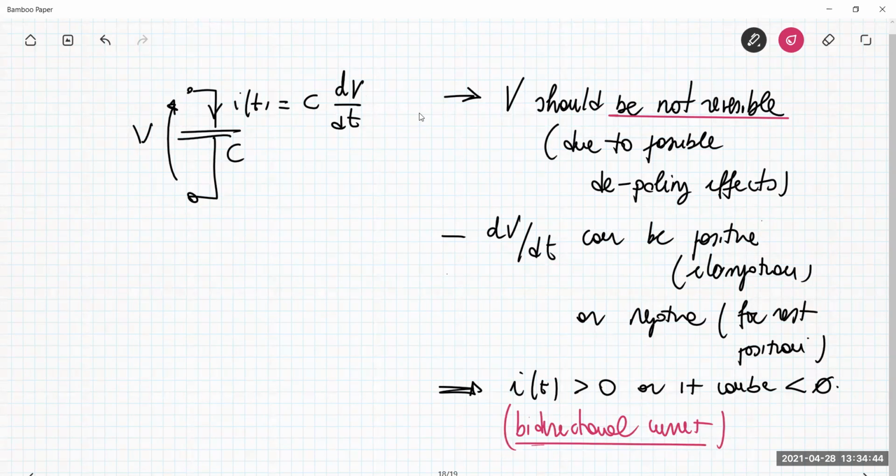Typically, this kind of requirement is most of the time obtained by using a linear driver. Linear driver means power operational amplifiers arranged in a way that they work for driving this kind of circuit. This is what is most of the time done. Of course, when you use linear drivers, operated in their linear operating region, it means that you have higher dissipation. This is always the situation that you have to consider in linear applications.